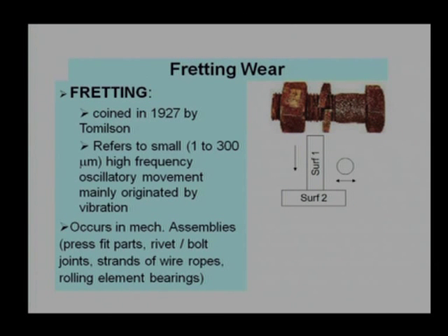We know very well when we are applying force, there will be some asperities, an irregular surface, and one surface has to climb on another surface. Quite possibly we will apply some force of low magnitude, and the surface will move on a micro or nano scale and come back. That will not be easily diagnosed from the outside, but it is happening, and that micro motion, that low amplitude motion, is causing the fretting wear.